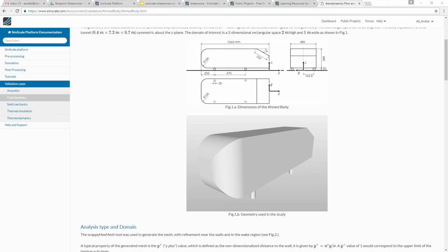The second part of the question is a comment that 5-hole probes cannot really be used in backflow regions of the flow. Ahmed is absolutely right with that comment. The 5-hole probes have an angle of acceptance which is directed towards the probe. So if you have backflow, you will not correctly measure the flow. But that is a problem inherent to the 5-hole probe. You can still use the data to visualize the shear layers. If you look closely at the comparison of measurement and experiment that Ali showed, you see that exactly in the separation zone the data does not compare well, and this is due to the 5-hole probes that do not measure correctly in this area.